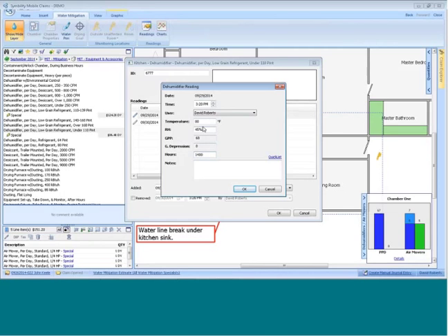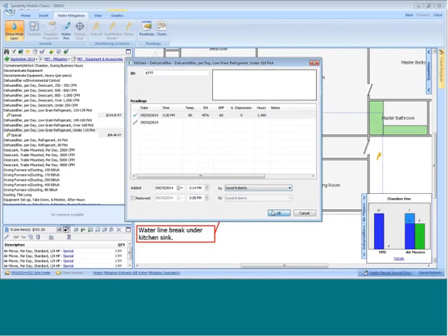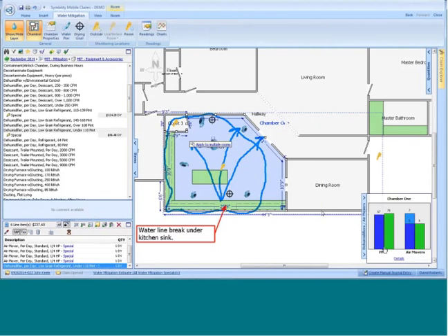And you'll notice, by the way, it's actually telling me, based upon these readings, what my grains of moisture per pound of air is going to be. It's calculating that for me. Now when I do that, you'll notice this green bar pops up over here, because based upon what I put in, which in this case was a low grain refrigerant under 110 pints, it's now telling me that I'm well within compliance of what was required, based upon those parameters. So that's how you place equipment into here.